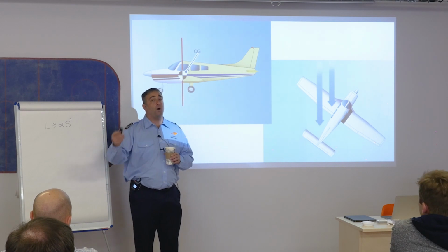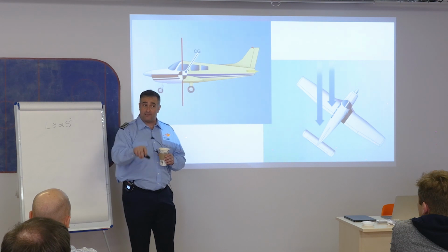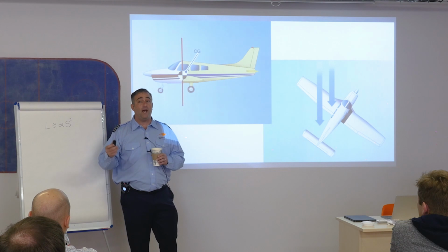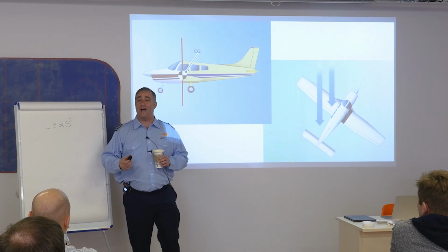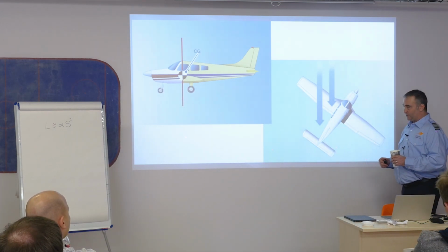I could do what's called a forward slip to land without flaps and still increase my descent path without increasing the speed of the airplane. I can do that easily, but I have to purposefully do it. The airplane is not designed to do that. And that's another one of the maneuvers that you'll do during your private pilot certification.